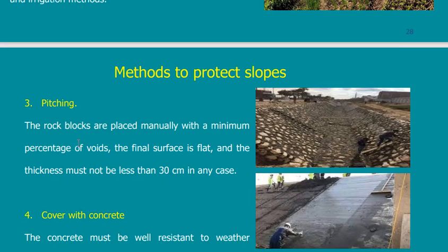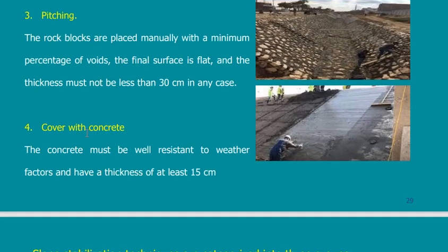Pitching, what we call in Arabic tadbish. You might have heard this a lot. In many places you find higher levels and lower levels, and between this there is a slope, and they go with rock blocks and place them next to each other, and sometimes they add mortar in between. So this will be the shape. This is pitching. Sometimes they cover it with concrete slabs.